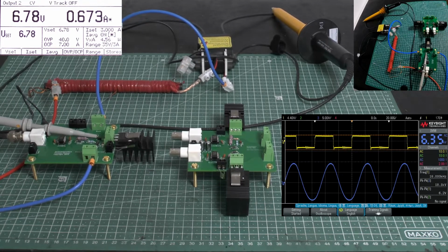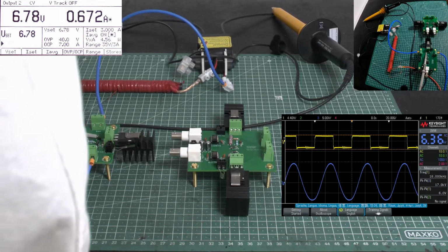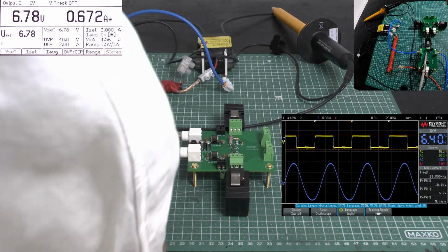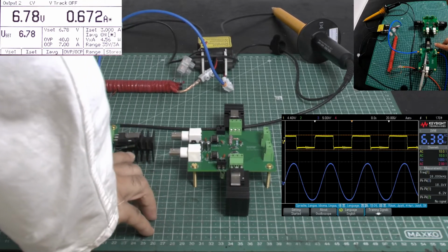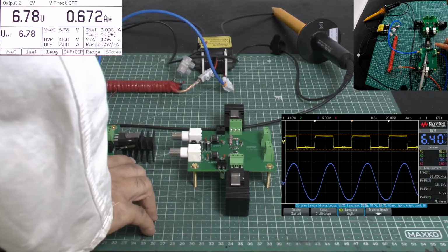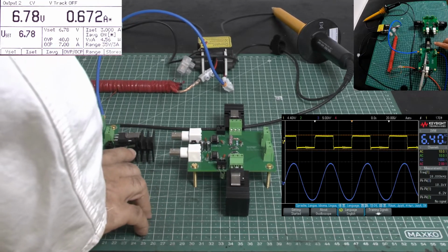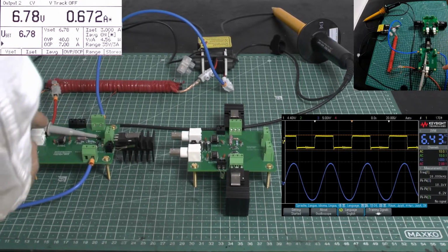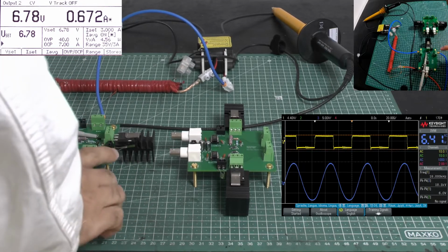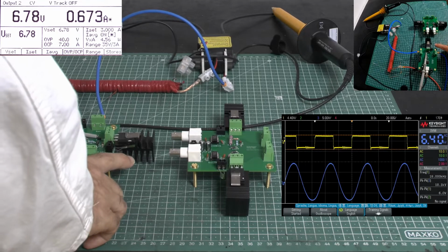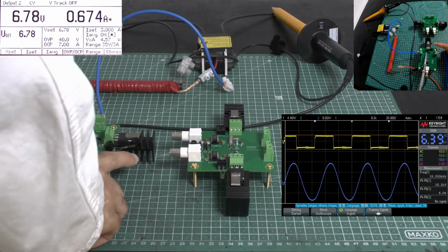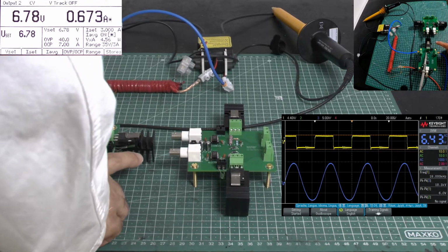So 4.57 watt is this, and you see here's a small ripple. What I didn't talk about, I had it in the last video, is I have a small smoothing capacitor, a gate capacitor which I indicate. I have also the RC snubber circuit which I don't use today. I use a smoothing gate capacitor which allows for very, very small ripple.